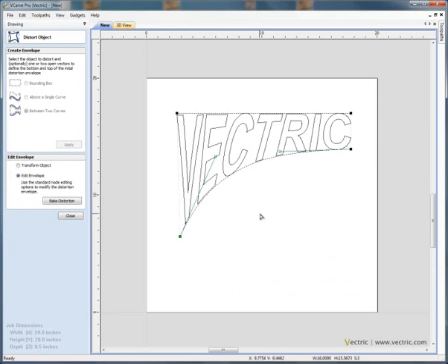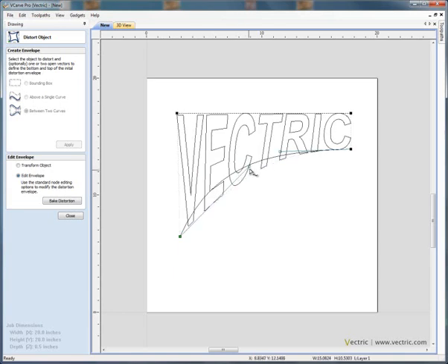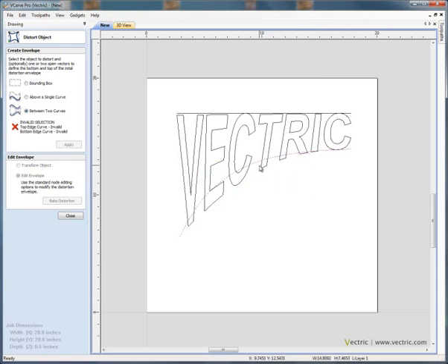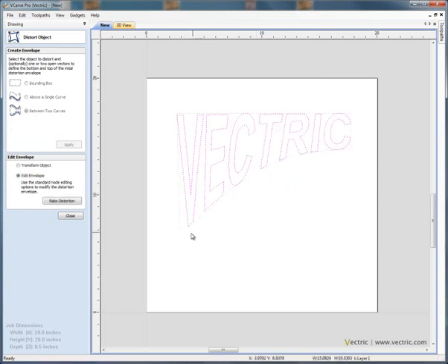We can now go in and use the editing tool. So although we've fitted the curves, we've still got Bezier control here. In fact, what I'm going to do is just escape. Let's delete the original lines. So shift and delete. Select the distorted object, and here we've got the option. The software knows it's a set of vectors that have been envelope distorted. We can say edit the envelope, or we can transform the object.